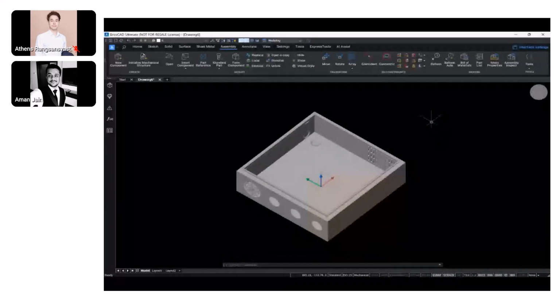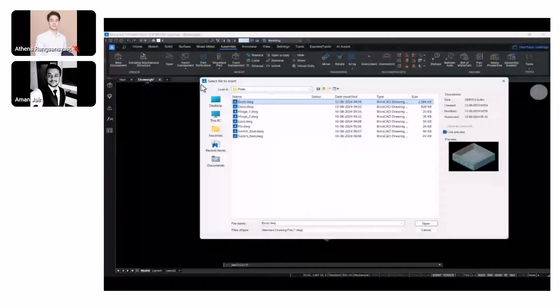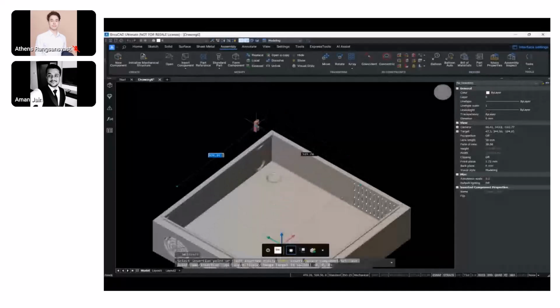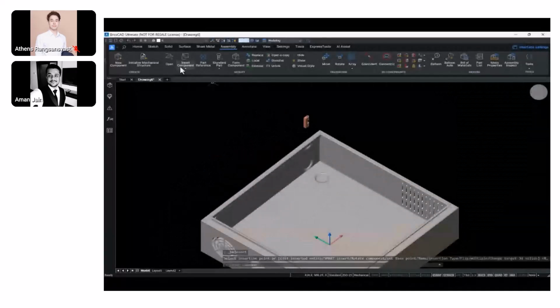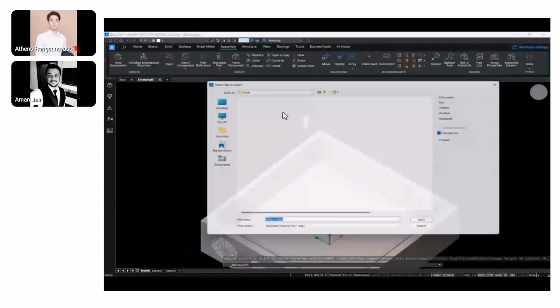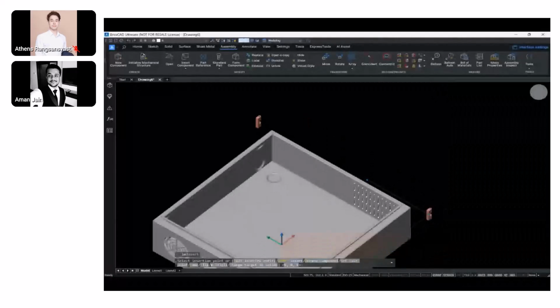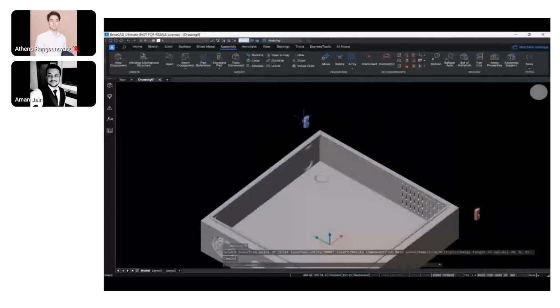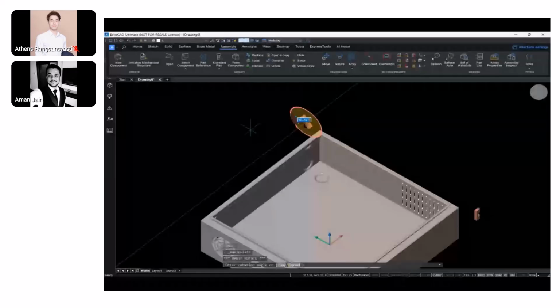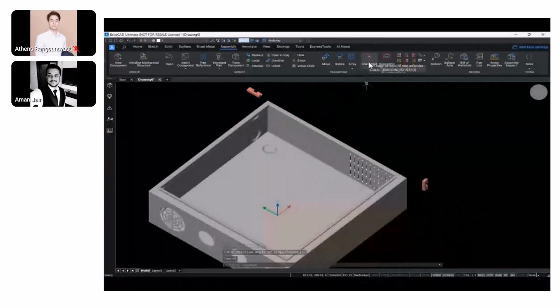So this is the main assembly, and inside the main assembly as well, we can insert components. So it need not be in a particular order, like we saw with the door, where we need to create the subassembly first, and only then will we be able to create the final assembly. It's not like that. These components, when we insert them, will be specific to this particular file. So any change across these hinges would be reflected in the main assembly file. Okay, that is how it works.